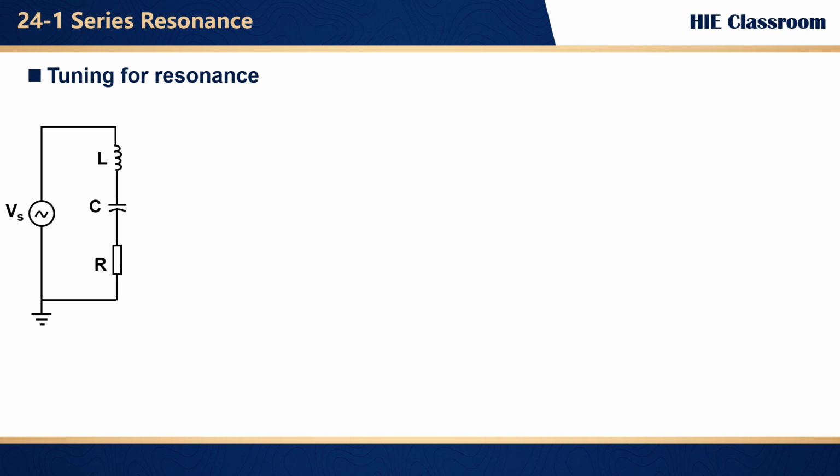Okay, let's work on tuning a circuit to catch that resonance frequency we've been talking about. We already know that the formula for the resonant frequency is Fr equals 1 over 2 pi times the square root of L times C. So if L and C are set, the supply frequency has to match Fr to make the circuit resonate. Makes sense, right? But what happens if the frequency is fixed? It's like it's coming from a source you cannot change. Well, then you can adjust either L or C, or even both, until the circuit is resonant at the given frequency.